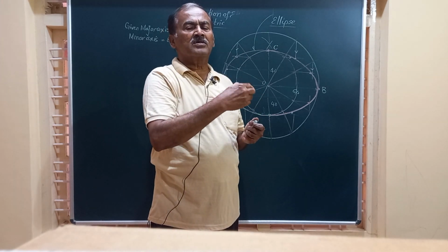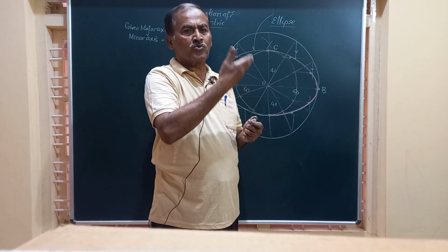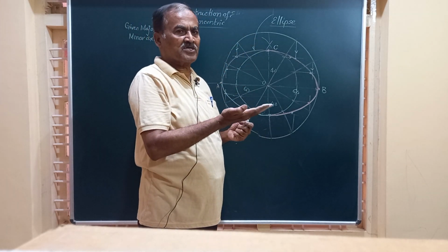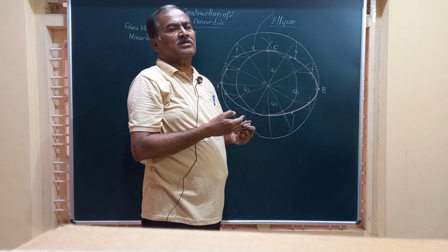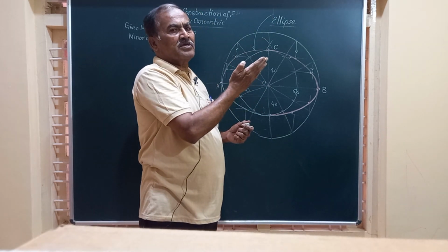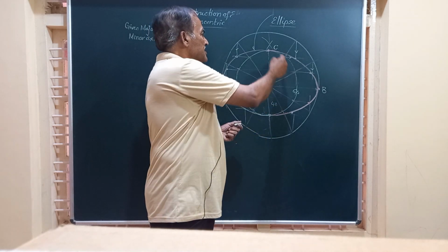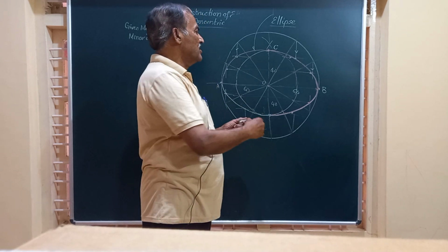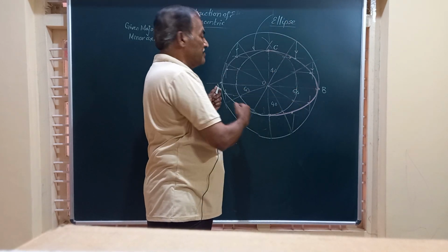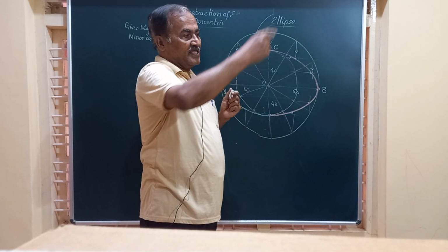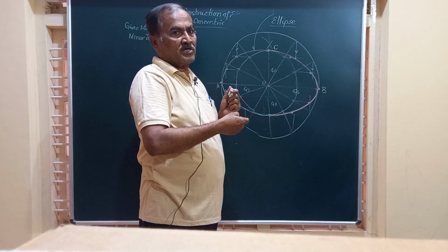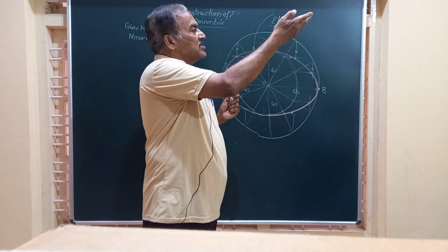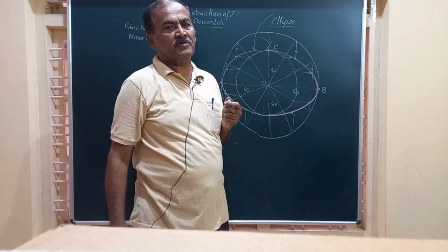This ellipse is a conic section which is obtained by cutting a vertical cylinder resting on one of the circular ends by a section plane which is normal to VP and inclined to HP, and the minor diameter is equal to the diameter of that cylinder, and the major axis, that is AB, is equal to the length of the section plane along the cutting plane. So that particular again depends on the inclination of the section plane with the VP.